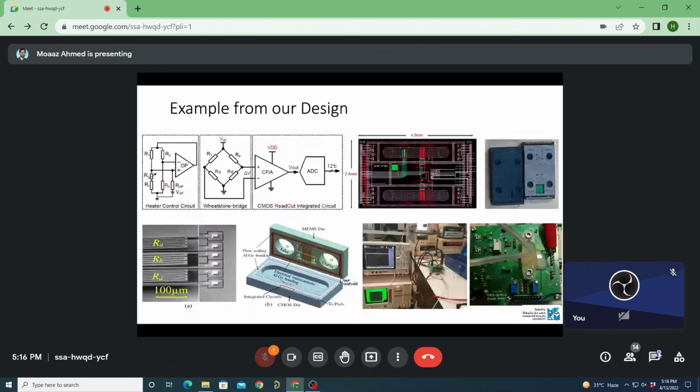So the next slide is how we do the design. What we do is actually nested chopping. We have primarily a current feedback instrumentation amplifier, CFIA. We have 2 sets of transconductors, GM in and GM feedback, followed by a 2-stage amplifier, second and third stage, because when we have 3 stages, we have nested Miller compensation.